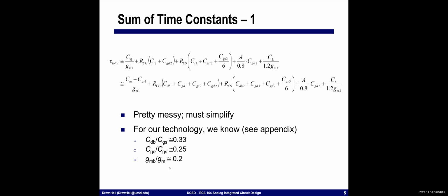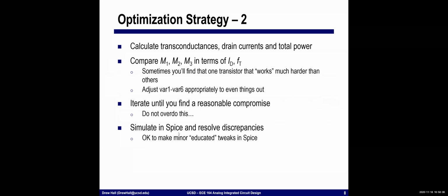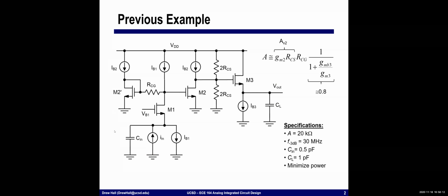You had it in one of your optimization strategies. You said like simulate the parameters in SPICE. I'm not entirely sure what you mean by that, because you also have it in this. Yeah, simulate the whole circuit. We're going to simulate the whole circuit, but you'll notice that even here, I could replace a lot of these with transistors, and I'm not doing it intentionally, right? So IB1, IB2, IB3, these could all be transistors. Even in this simple example, I'm leaving them as current sources.